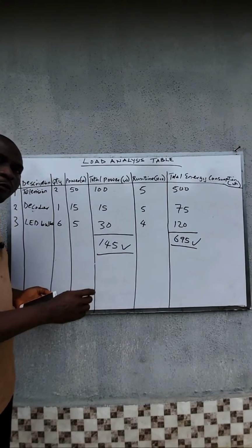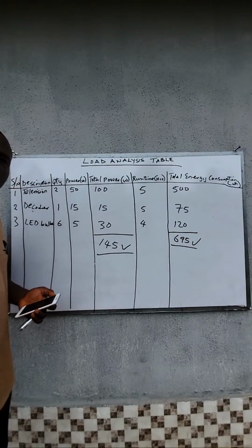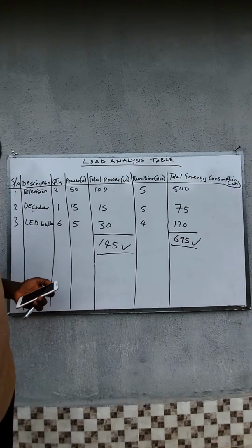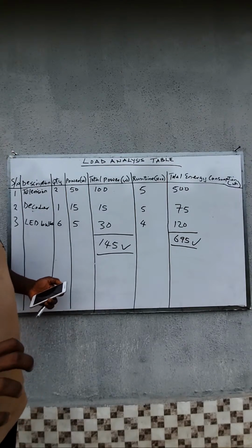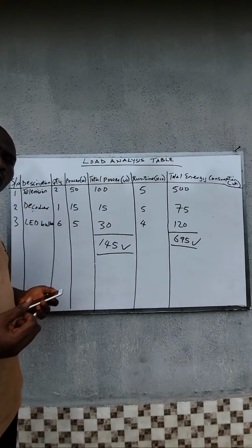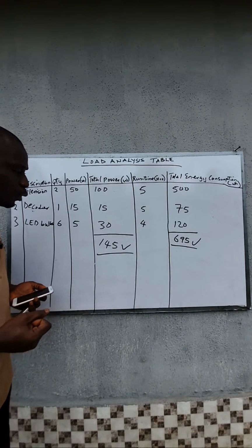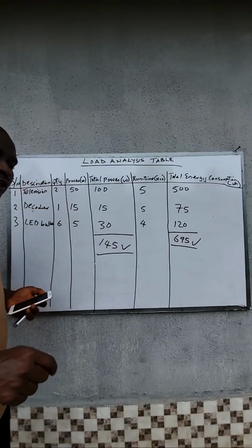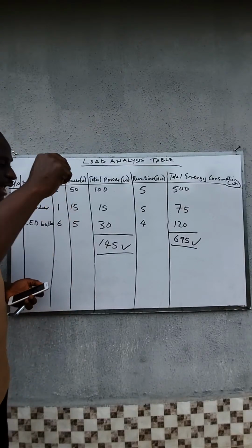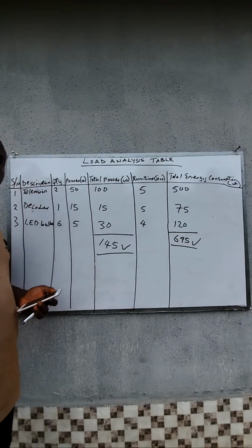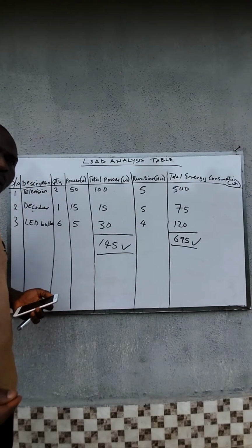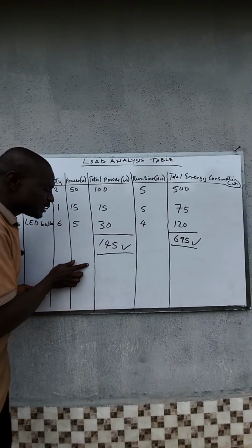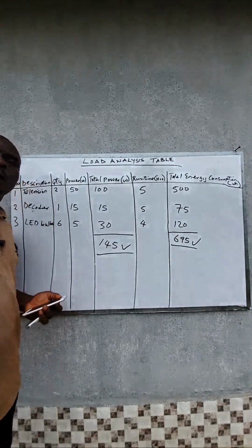Remember that such power will not last for long, maybe some milliseconds, a few seconds. Once it starts, you see it running at its normal power, but it needs that high amount of power or current to start. So you need to take into consideration that starting power, else the inverter will fail. It will not be able to carry that load.